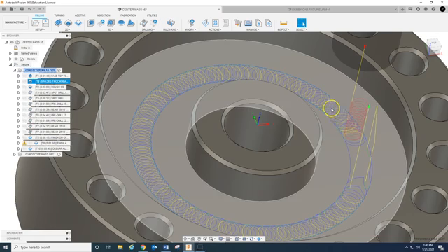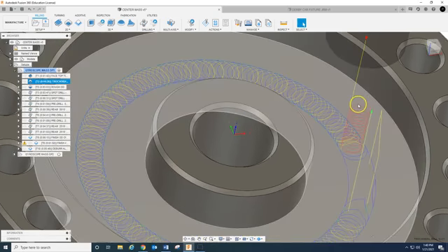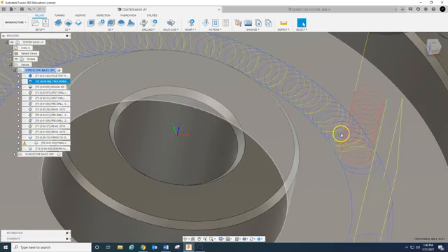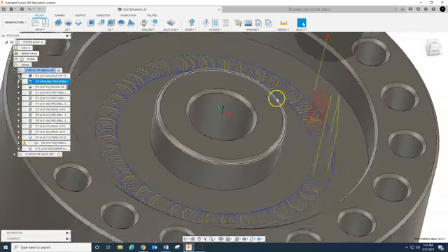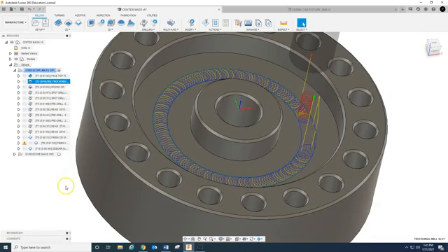All right, the blue lines here are cut lines, and the yellow lines are high feed lines, meaning that it's not going to rapid. Instead of going G0, it's going to go G1, like 750 inches a minute. It just makes it position a little bit faster.